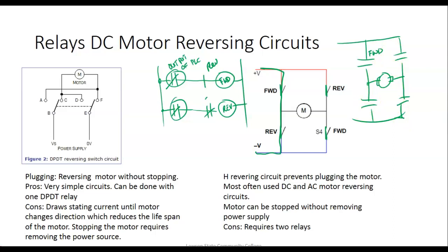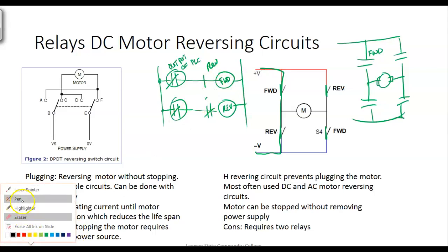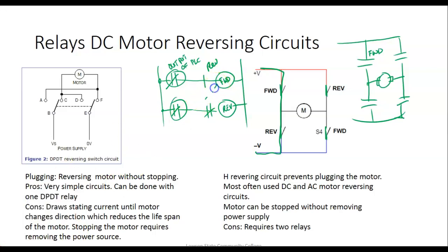Now, one of ours has it. I'm sorry. And then, of course, what we also do over there is that they also have what we call a mechanical interlock. And I think I showed y'all that, where if I manually push down on the forward, it wouldn't let me push down on the reverse, on the manual override. So that's the best way to do it with both electrical and mechanical.